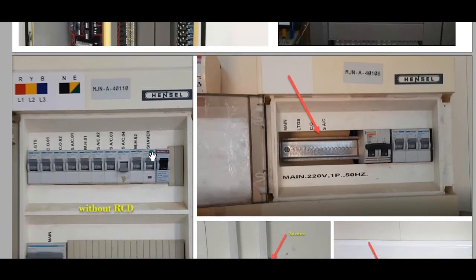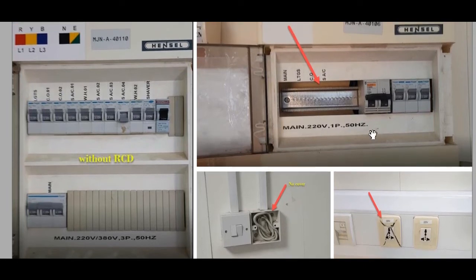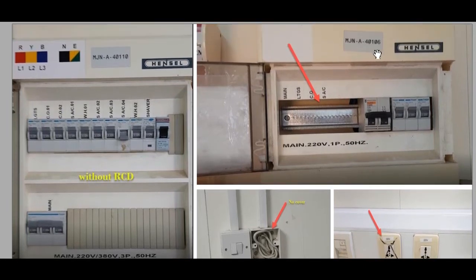Here are samples from my inspection. For example, have you seen this one? This is the DB number, and as you see here, we have a lot of opening areas. It is not allowed because this is not within the IP standard, so all these holes must be closed with the required materials to make all this area closed. So in this case, the DB is brought back to the required standard.